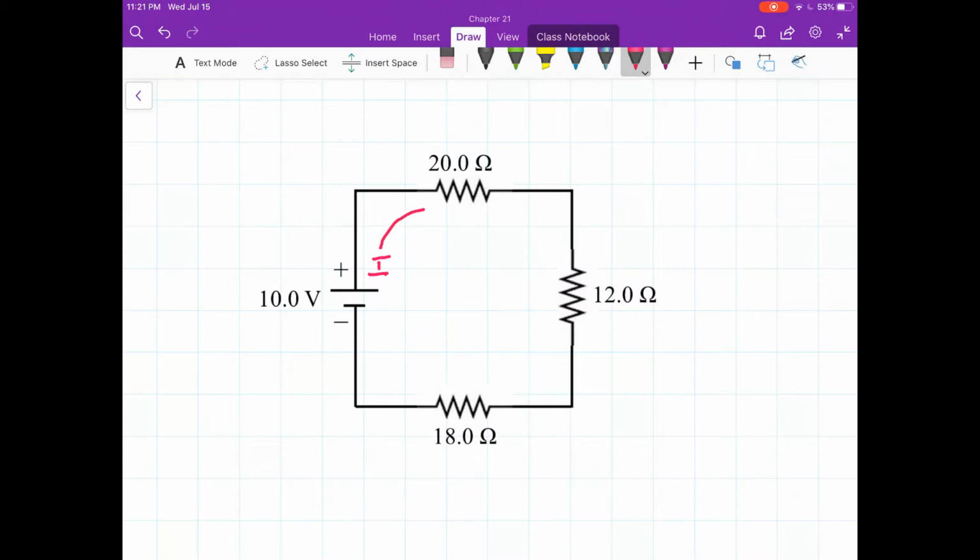It's going to flow through the circuit, through the first resistor, through the second resistor, through the third resistor, back into the battery. Series resistors, what goes in one is going to come out, go into the next, into the next. And remember, in series, everything has the same current. It may have different voltages, but the resistors will have the same current.